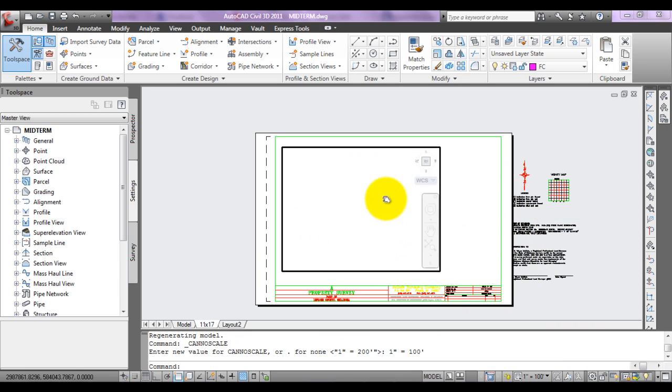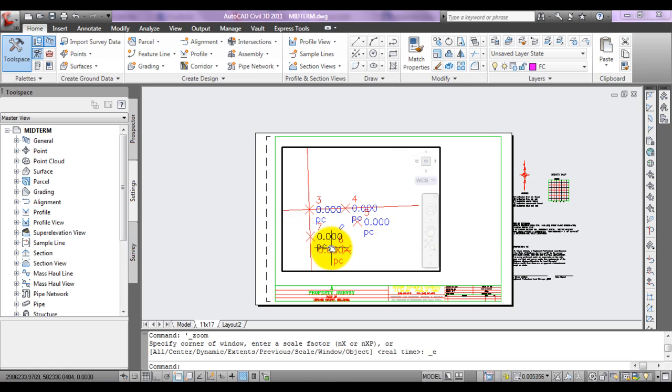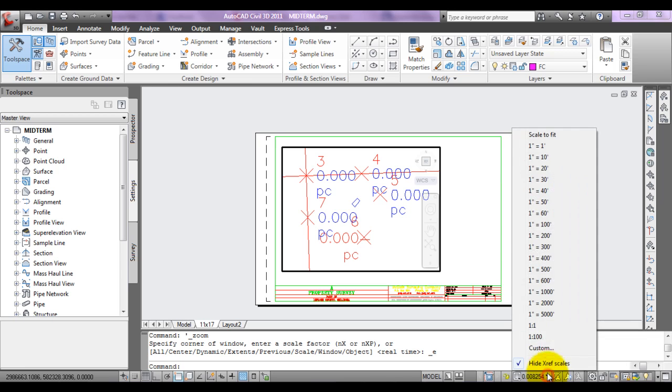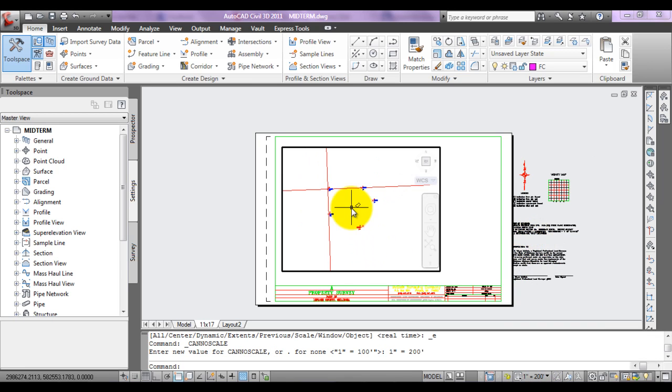100. Apparently, let's center on our property area here and change the scale. There we go. Okay, and if you'll notice, for some reason, some of our stuff is not showing up. The property line's not showing up, the fence, the road's not showing up. And that has to do with what layers are turned on and turned off.